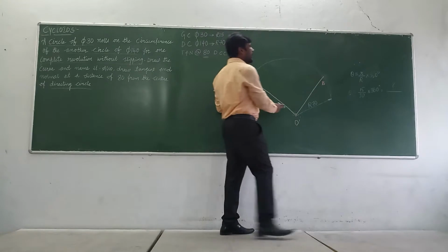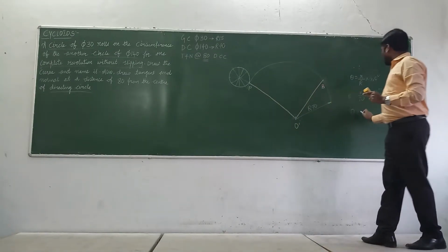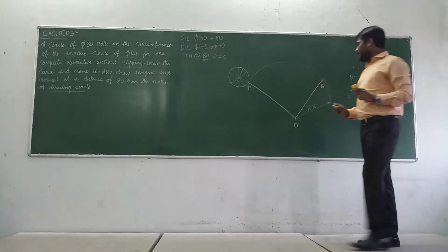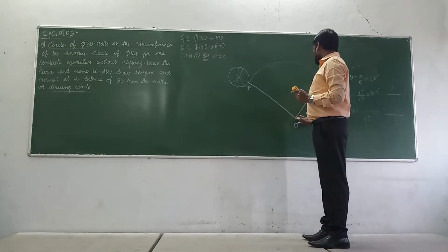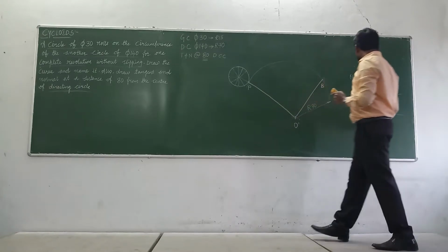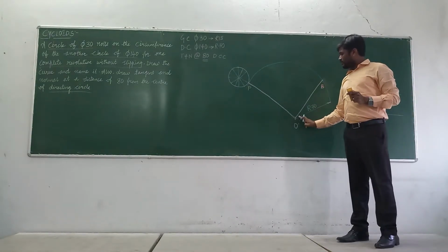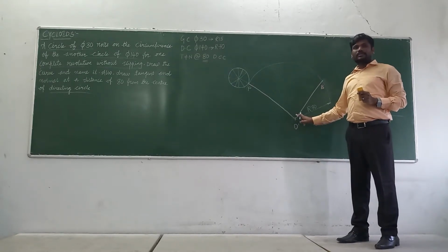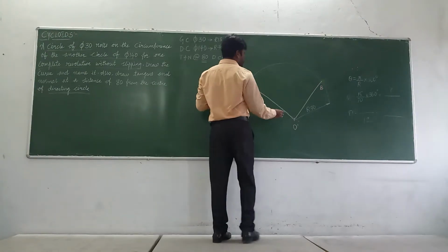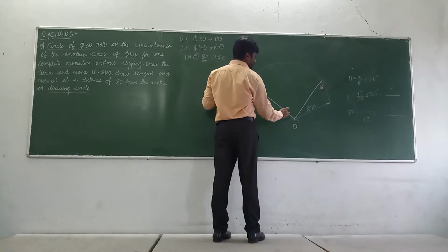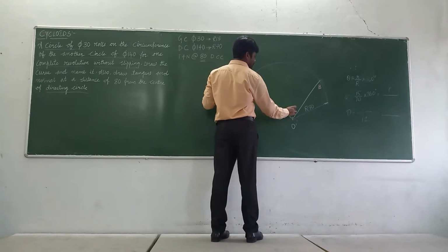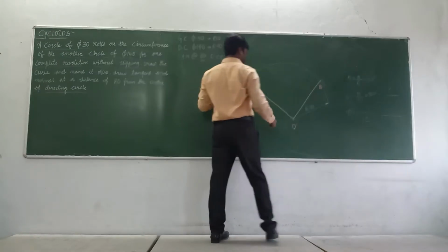You know how? You got an angle here. Whatever angle you got here will be divided by 12. You will be getting a value. Taking your compass with that value, mark the 12 divisions. Those divisions you are going to mark here as points like 1, 2, 3, 4, 5, 6, 7, 8, 9, 10, 11 and 12, and so on.